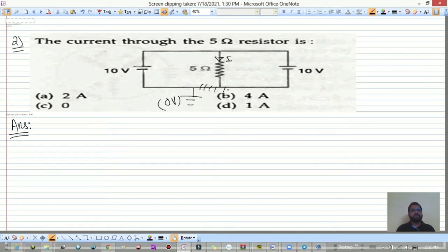So over here it is short circuit, everywhere as you can see it is short circuit. Over here also this is 0 volt, over here also 0 volt. Okay, so if this is 0 volt, this is 10 volt. Indicates at this point it is 10 volt only, because this is 10, 10, 10, short circuit, isn't it? Everywhere it is 10. Okay, so I hope this is clear.